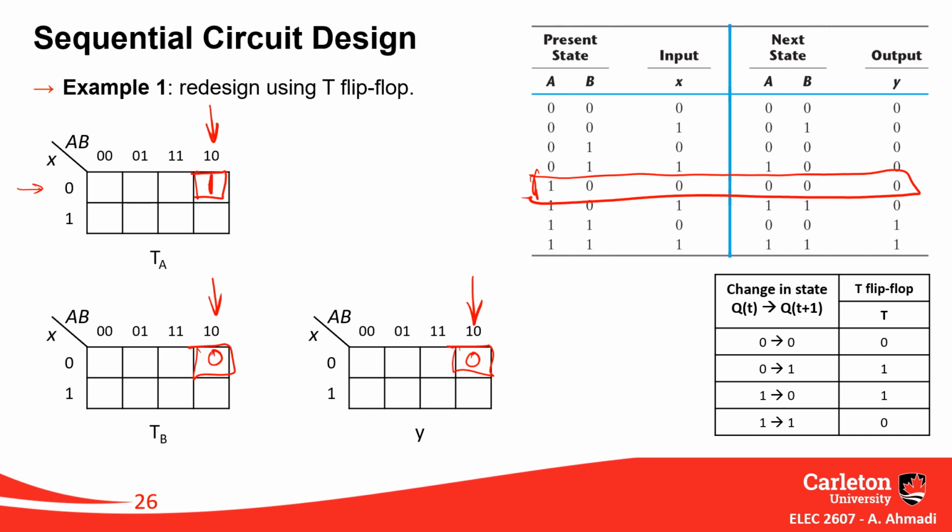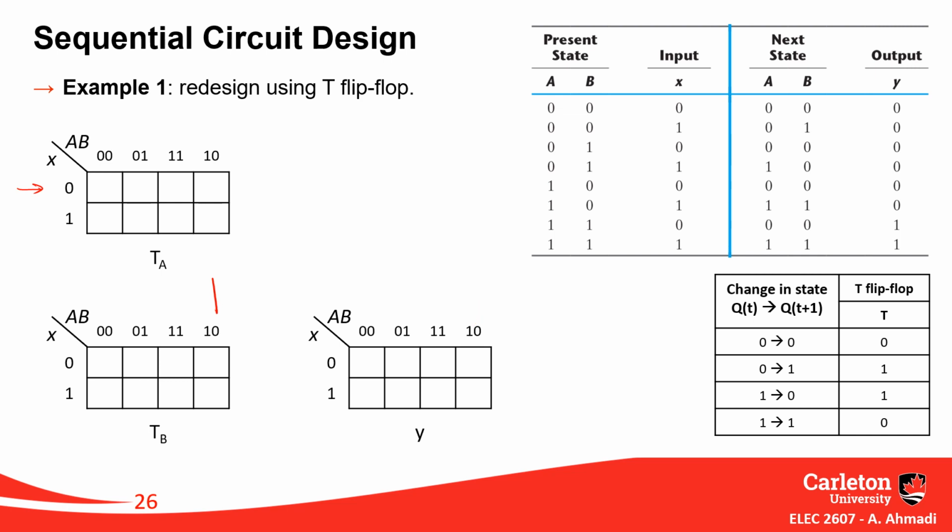In that way, you fill up the table. Every single value in the table will be calculated based on that, and you have a design here. And you can make your circuit implemented based on that, like this. When it's implemented, every cell of your T flip-flop input tables are filled up, and then you can design the circuit using this logic simplification.